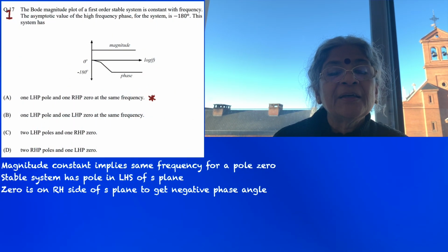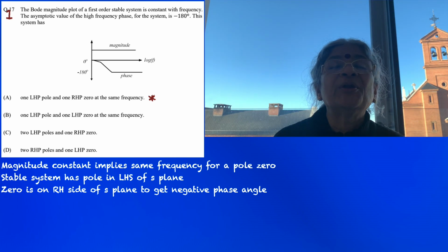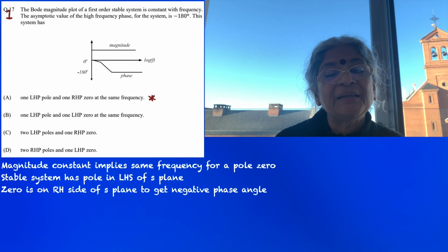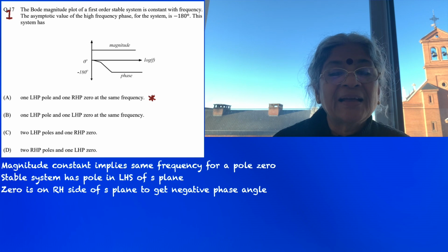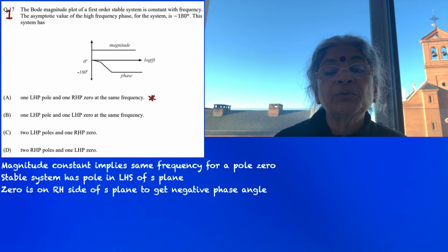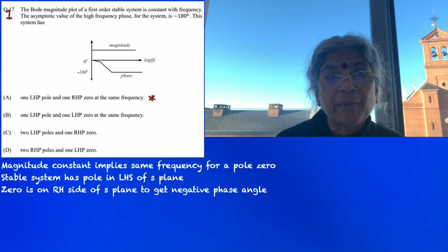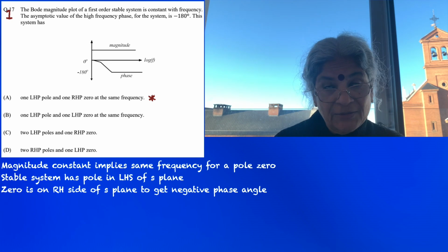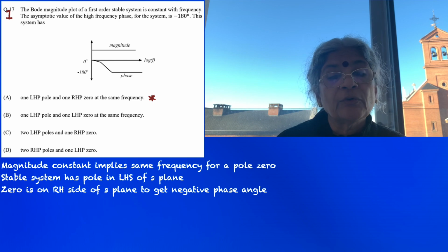What do you see? You see two concepts of Bode plot put together. So I would say that you can look at the phase angle, angle G(jω) shown there, and we see that it goes from 0 to minus 180 degrees. Okay, so this should immediately bring to your mind that there are two poles, because two poles will contribute to a total of minus 180 degrees.